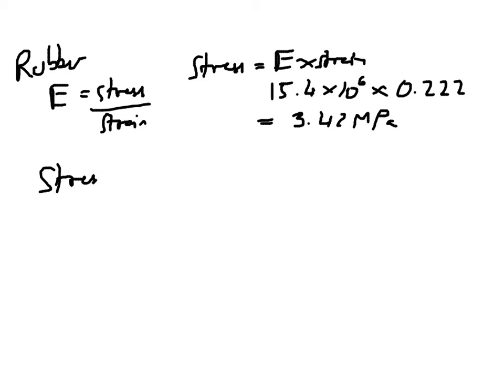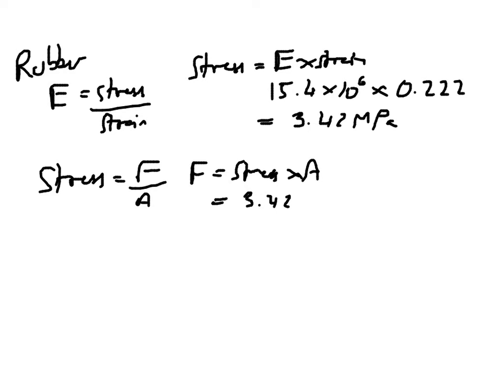Stress is force over area. So force is stress times area, which is going to be 3.42 megapascals, or 10 to the 6, times 0.1 squared, which was your area of contact. And that equals 34.2 kilonewtons.